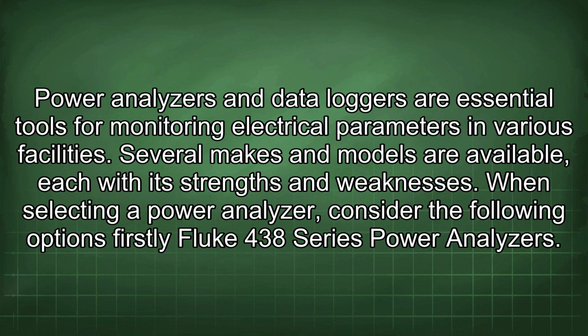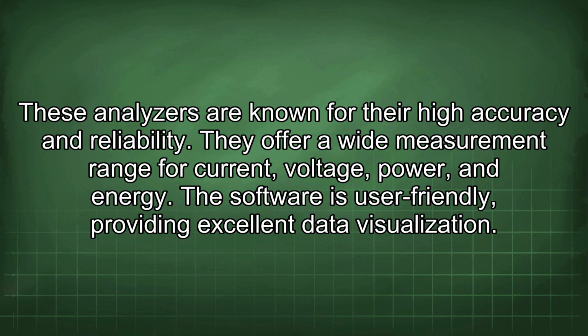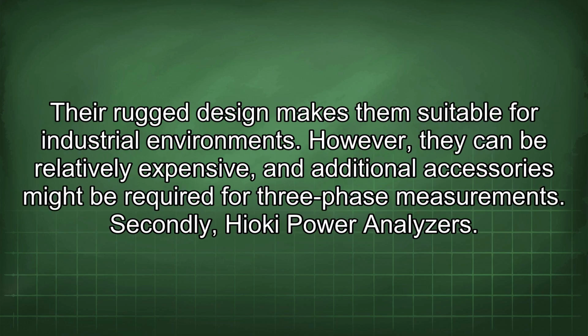Firstly, Fluke 438 series power analyzers. These analyzers are known for their high accuracy and reliability. They offer a wide measurement range for current, voltage, power, and energy. The software is user-friendly, providing excellent data visualization. Their rugged design makes them suitable for industrial environments. However, they can be relatively expensive, and additional accessories might be required for three-phase measurements.